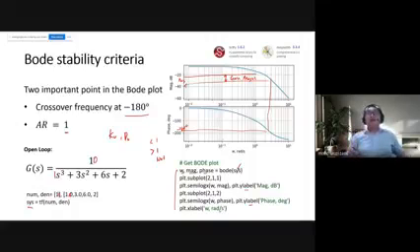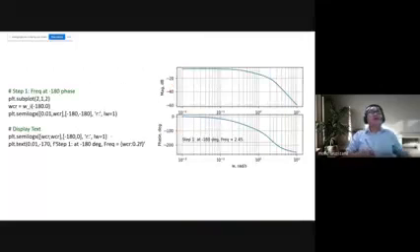So in this case, now I want to apply this information to study the stability. First step, I want to check at negative 180 what is my frequency. So in this case, from here, I want to know this value. How do I do it? So this one, WCR, and then WI. This is the frequency at negative 180.